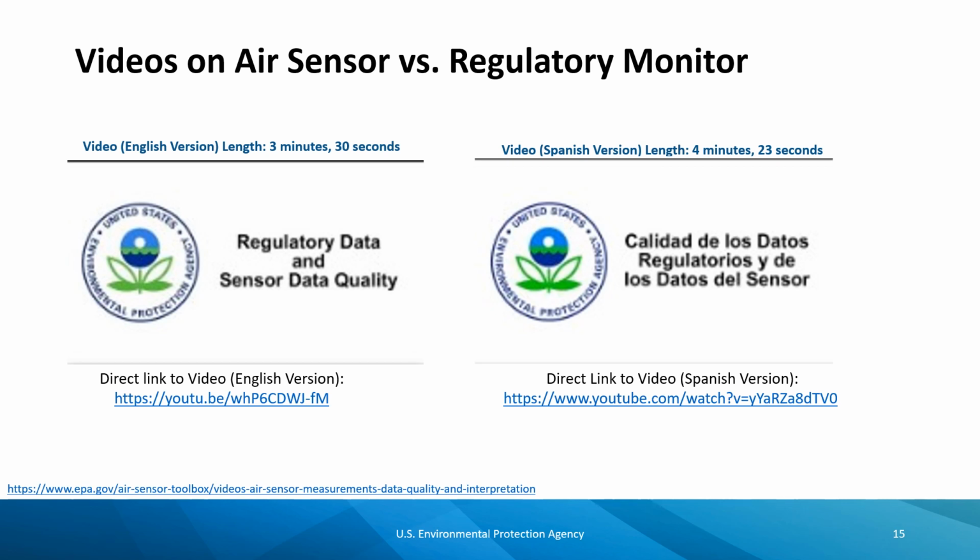They may provide less accurate measurements than regulatory monitors and may not operate well in extreme environments, like high temperatures, humidity, or pollution. Also, many people operate sensors with limited, if any, quality assurance. Currently, some sensors lose their ability to take accurate measurements over time. Finally, sensors may provide data outputs every minute or second. Note, with more frequent sampling, there can be greater uncertainty in the measurement itself and how to interpret any potential